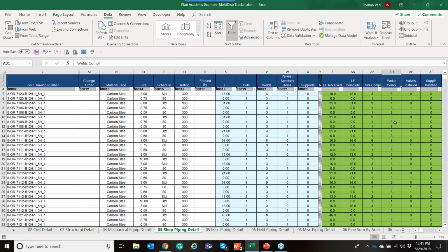We've even seen on different projects where the welds are actually done in weld inches, so a larger diameter pipe with multiple passes is more work. In this case, they did that takeoff based on diameter and then the number of total man hours they applied. So the welds are equivalent based on the total number of hours on that ISO or drawing.